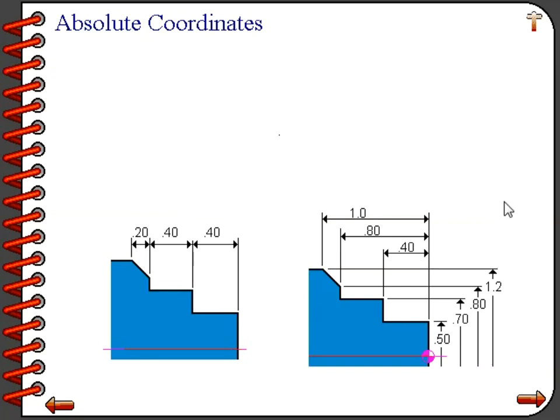On the right side of the screen, you will see that all of our dimensions along the Z-axis are coming from the right finish face, program 0. In this example, each dimension coming from there goes towards the left. So our first dimension, 400 thousandths: to get to that position with absolute coordinates, we would command Z-0.4. The next step is an 800 thousandths dimension.